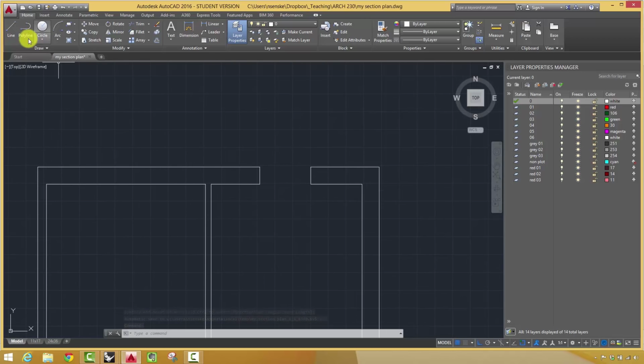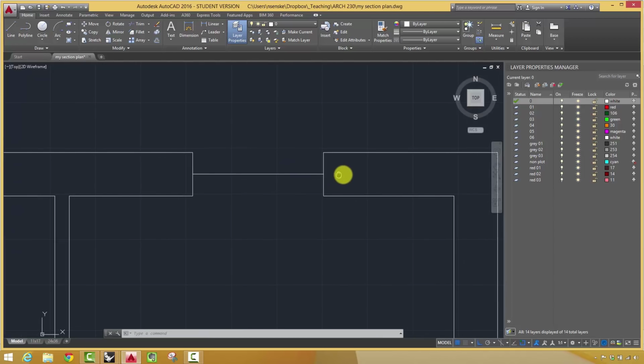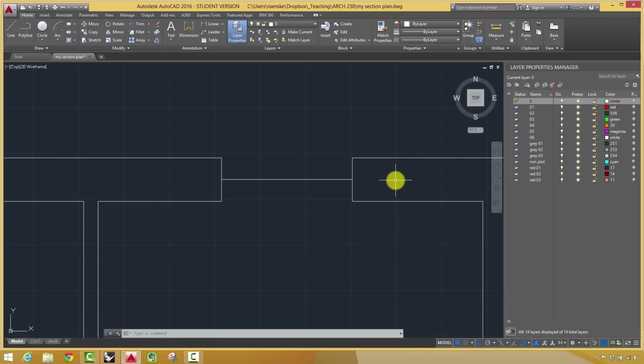All right. The other door is going to be a standard kind of door. So you draw a midpoint to a midpoint. When you're drawing a door, you have to think about where it is in the wall. In this case, it's going to be centered, and then you want to do the same thing. So I'm going to go ahead and offset the door. Doors can be 2 to 3 inches across. I'm going to make it 3 inches, so it's 1.5 inches in either direction. Delete this, and then I'm going to make it a square again.